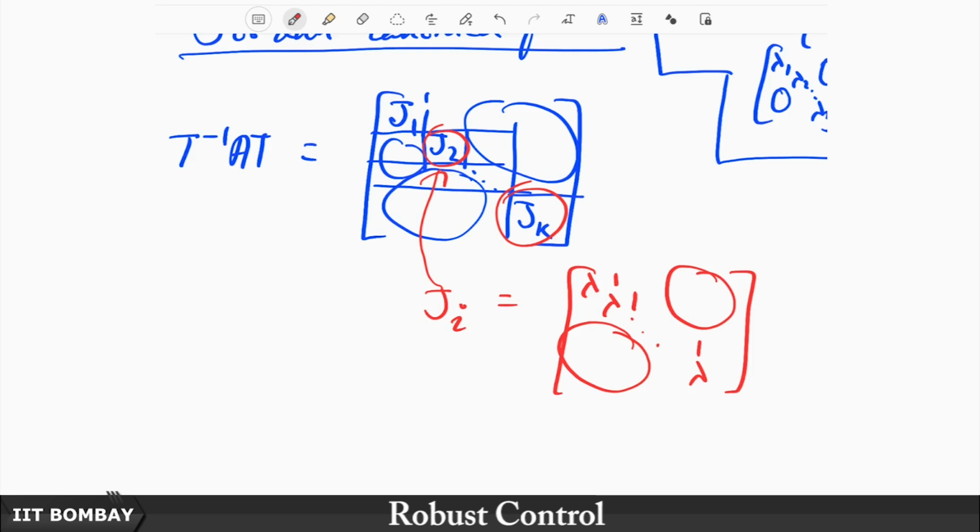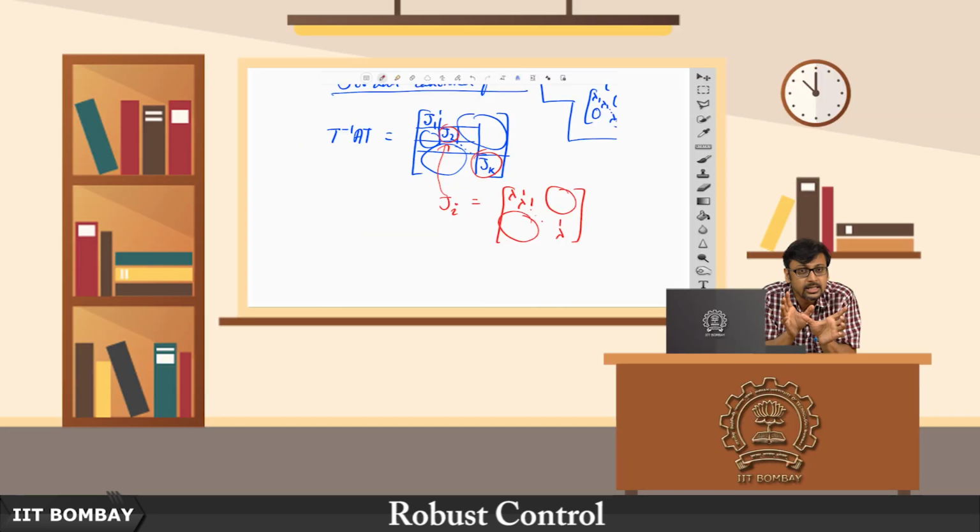Similarly, if you have a dynamical system given by x dot is equal to Ax plus Bu, and if the A matrix happens to be upper triangular, then the last equation is at least completely decoupled from the rest. So, the last equation you solve for xn: you have xn dot is equal to something times xn, solve for xn independent of the others. Once you have the closed form expression for xn, plug that into the expression for xn minus 1.